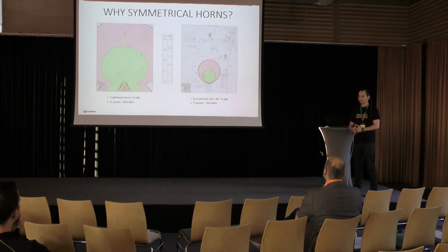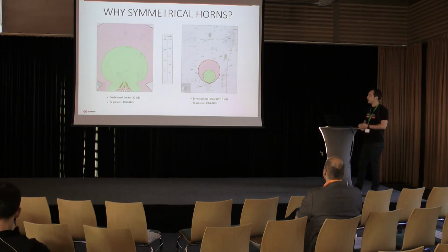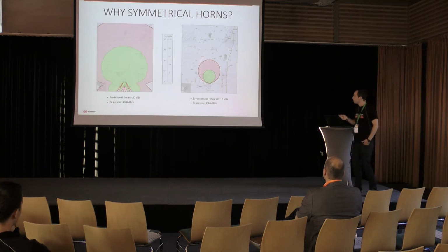All bad. This is why the spectrum is already killed, why everybody else is having problems with installing other APs. You can increase TX power, like we did in here as well. But if you can check, you're still spreading the signal only to the area where you really need it.